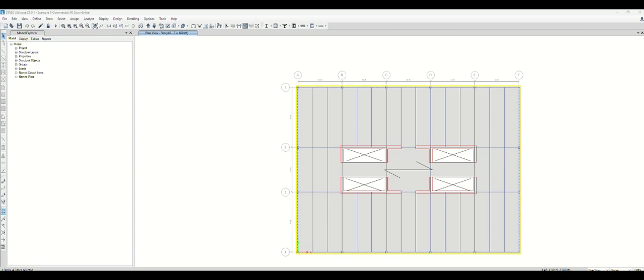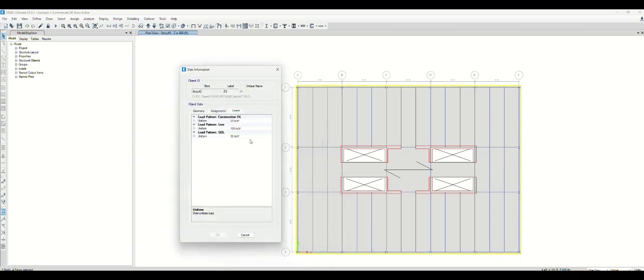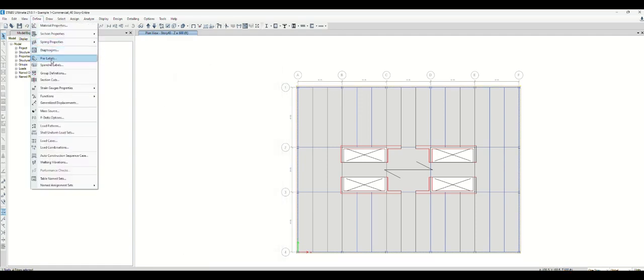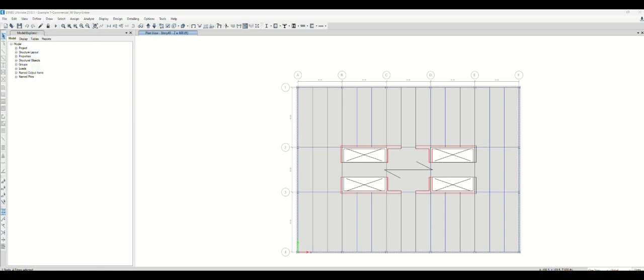And this model, I have construction load, which I'm not going to use for column and beam design. This is only for the composite floor framing beam design. So most likely we're going to use dead load, which is self-weight, and superimposed dead load and live load, right? So similar to the composite floor framing design, we're going to set up the load combination for